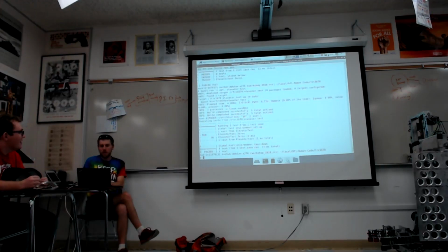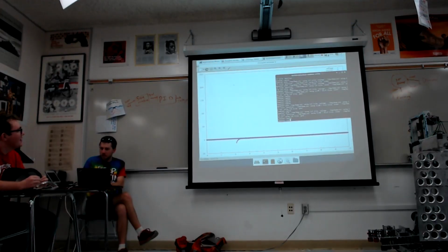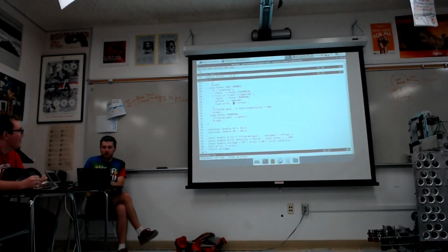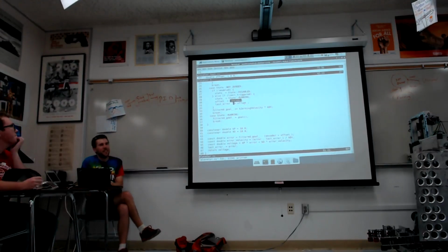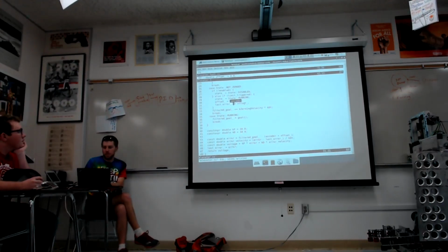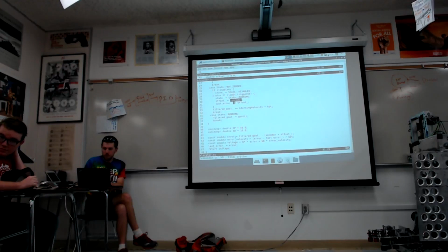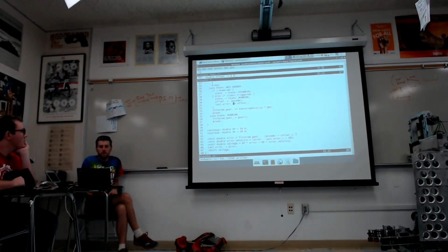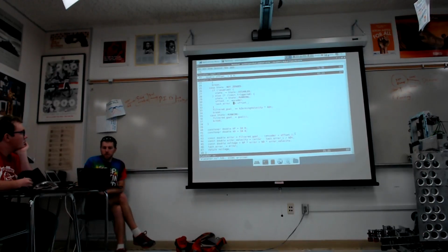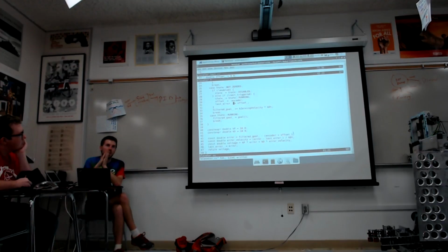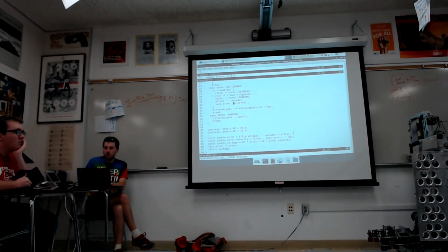Looks like there's something else still wrong. Oh, that worked for the same reason that encoder worked. Since our new error is basically going to be filtered goal minus encoder offset, if you set last error to that, then it should be the same. So the change of error over time should be 0. I think you can just set it to the same expression for error.